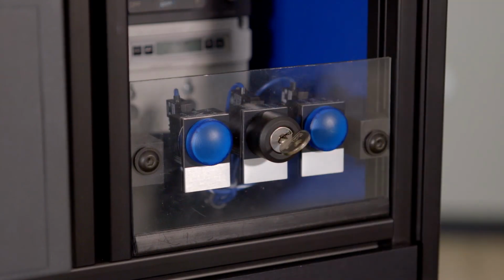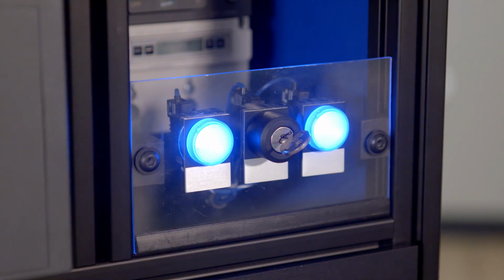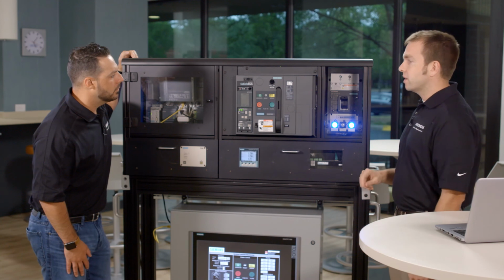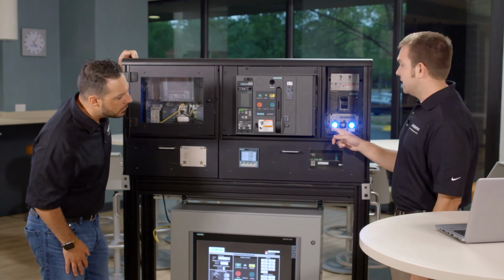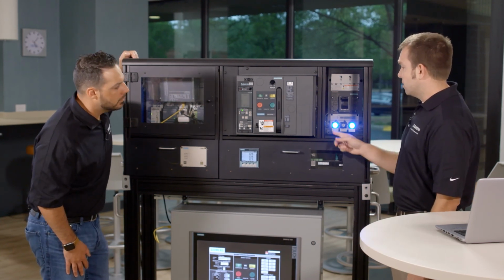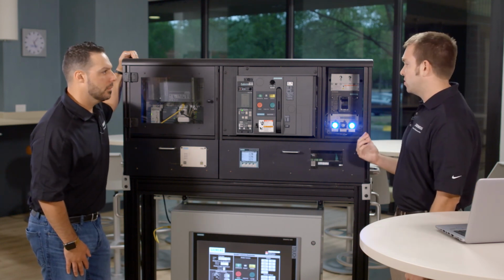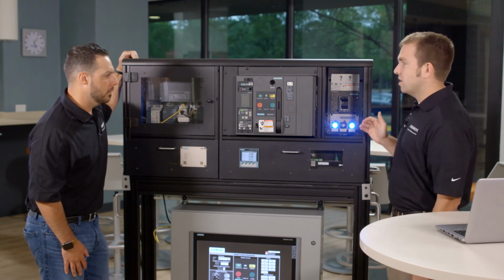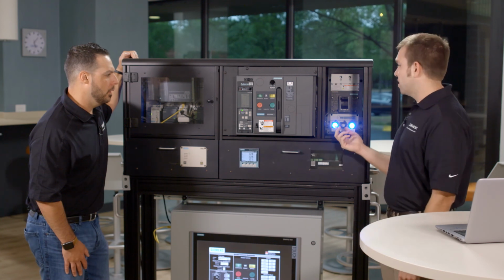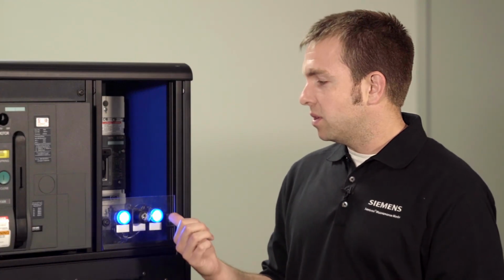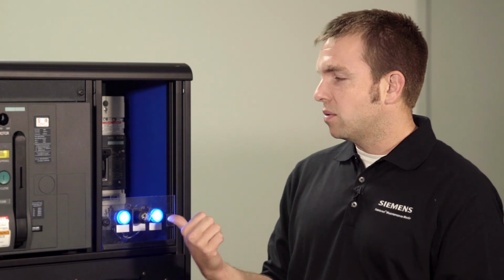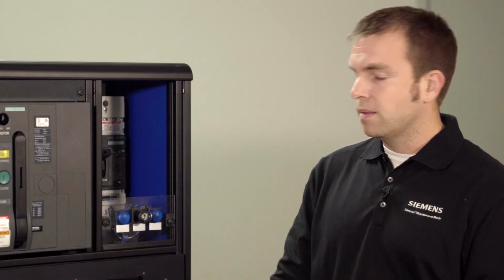Okay. So when I flip the switch, the smart controller is actually going to tell the VL breaker to go in maintenance mode over communication, and then the WL breaker. When these 2 blue lights come on, it indicates that it's in its maintenance mode. So it does it over a Modbus communication system. So the great feature here is, with this system, you can actually also do this remotely. So I'm going to turn it off and take it out of maintenance mode, and you'll see the system now tells the breakers to come out one at a time, starting with the VL and the WL.